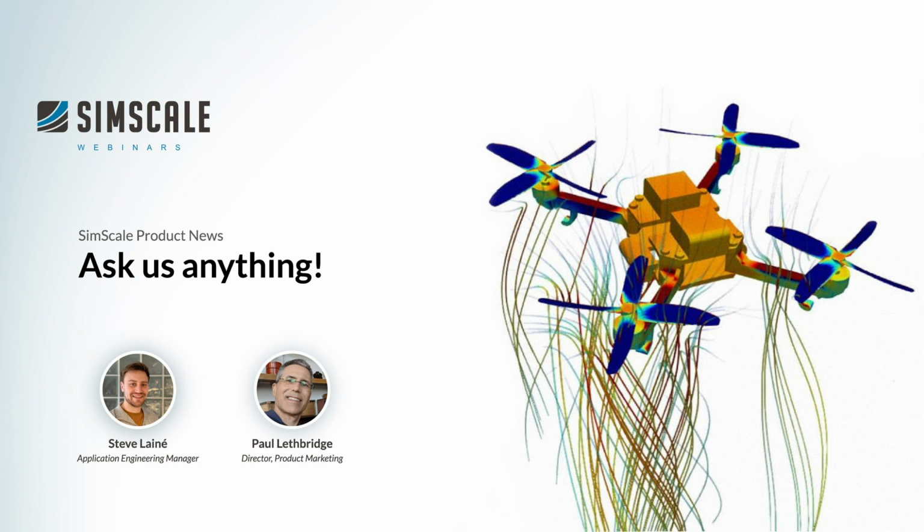So are we using the moving mesh method? Okay, yeah, it's a good question. At SimScale, we don't use a moving mesh. We're relying on the mesh refinement zones that we set up in advance and using those to be efficient. Obviously, we got these results in the space of 10 to 20 minutes per simulation. So we were able to get very efficient simulation results without the need for a moving mesh. If you want even faster results, you could, of course, take advantage of the symmetry of a drone like this, and then you could get results out in around about 5 minutes.